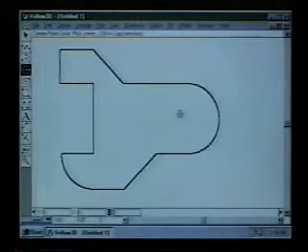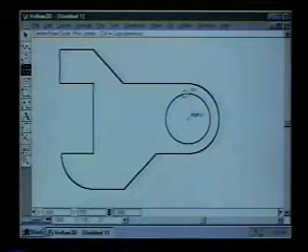So now I can come here, and I'd like to have a circle that's centered on this arc. But again, there's no help initially from the drafting assistant. All I have to do is, without clicking the mouse, go up and touch the arc by brushing over it. It wakes up the center point, and then I can go to that center point, and I see the word center so that I know I'm exactly on the center, and I can pull an exact arc here.